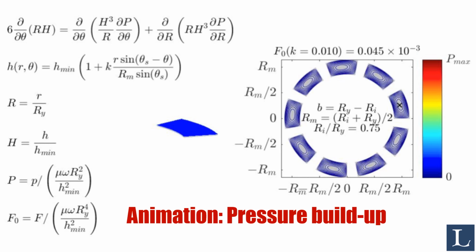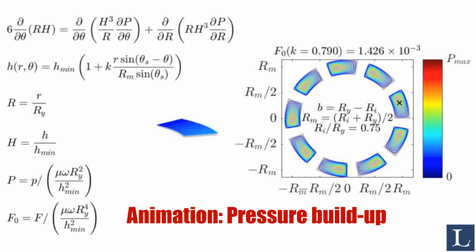And when I now press the animation to start, you will see how the inclination of the pad increases, and as it increases, you probably also noticed that the pressure distribution was shifting so that the maximum pressure was moving towards the trailing edge of the bearing. And also you saw the pivot point, marked here with an X, was also moving towards the trailing edge of the bearing.